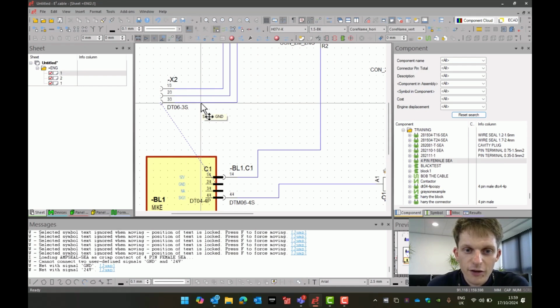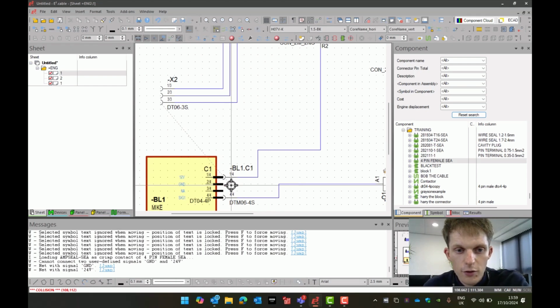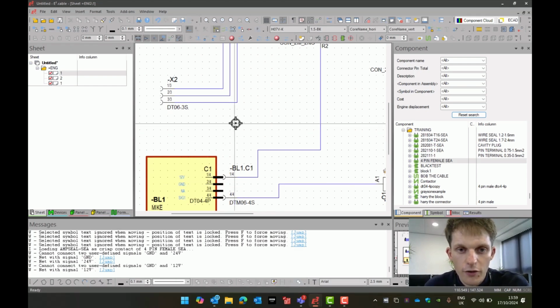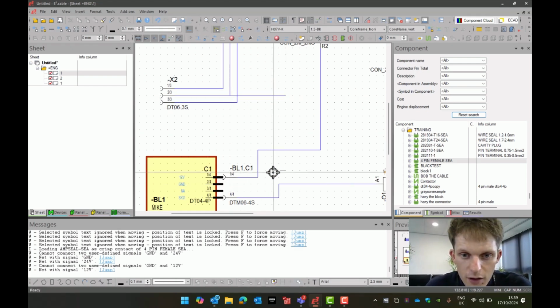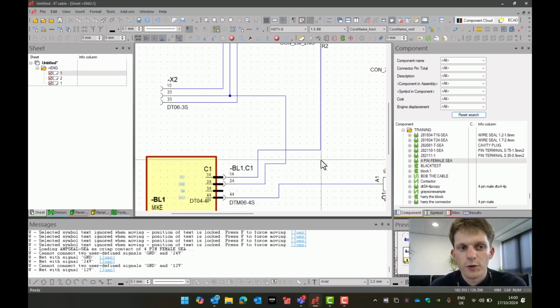So I hover over this line, it says ground. This is because this pin is a ground signal. So I could then therefore connect these 2 together, okay? So if I went on to press C onto my ground and brought it down to here, unfortunately my drawing is a little bit funky, but I'm sure we can fit it in. Let's pop it there, and then bring in that connection there. I can connect ground to ground, okay? So this is why they're fantastic to use signals in your project.